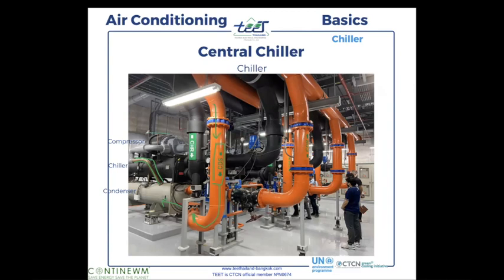And this is the compressor. So you see it's an air conditioning. You have the compressor and the refrigerant fluid. The refrigerant fluid goes out from the compressor and goes into the condenser. The condenser is not outside in the air, it's in the water, because we have to cool the refrigerant fluid by using the condensing water supply from the cooling tower.